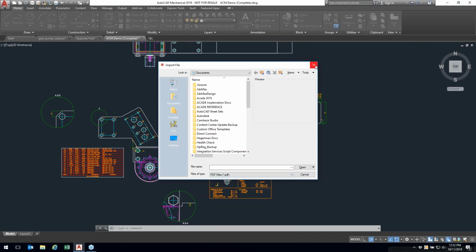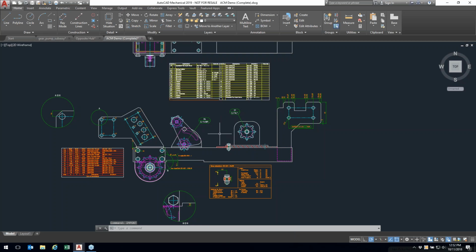The big thing about being able to import that data in here is that it is a 3D file most often. So you may want to consider using things like the flat shot command or the flatten tool within the express commands in order to turn it into a 2D profile that you can then work against. However, the big thing to think about there more than anything else is that we're dealing with 2D drawing tool sets, not necessarily a 3D drawing tool set as far as these commands are concerned. If you were trying to import it to then turn it into an AutoCAD file, obviously we can do that as well. So yeah, absolutely, we do have access to importing files.